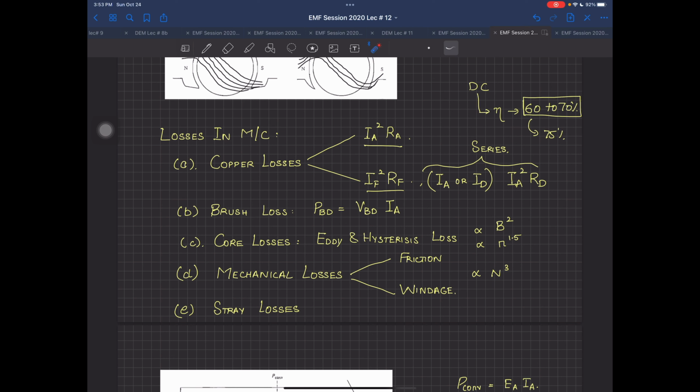In practice, when the carbon brushes slide on the commutator segment, the part we want to erode is the carbon brushes. We don't want to erode the commutator segment, because the commutator segments are made so thick that during the lifetime of the machine, maybe 40 or 50 years, or even after 10 or 20 years of long daily usage, they can still withstand it and the copper does not erode off.